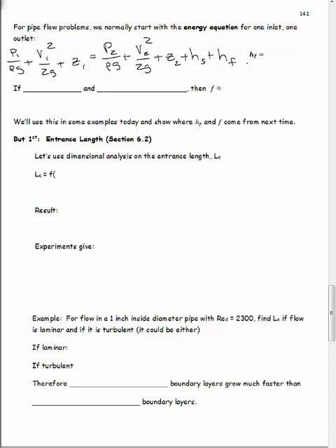Those are all those problems where we were putting our inlets and exits at free surfaces and at exits of the pipes and all that. Same kind of thing here. We're still going to do networks with pumps and all that kind of thing in here as well. So HF, now we're going to actually define HF. HF is going to turn out to be FLV squared over 2DG.